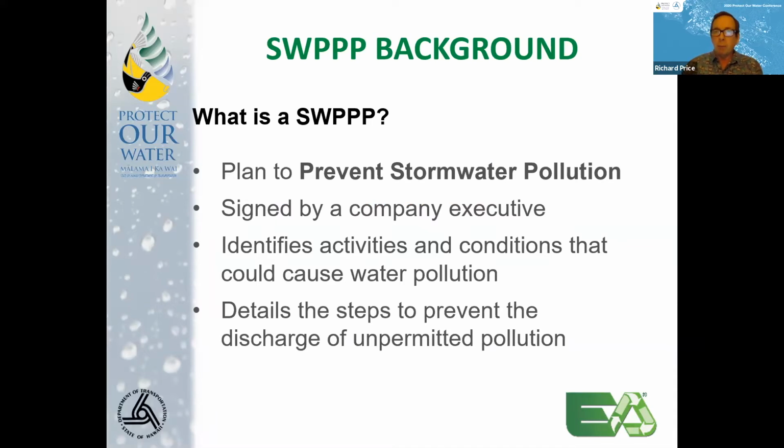That's an important point, because the construction general permit is a federally mandated permit under the Clean Water Act and has mandatory penalties associated with noncompliance, particularly for intentional noncompliance. And so if you, or in more cases your boss, is signing this plan because you told him it's good to go, they are personally liable, and the company is liable for what's in that plan. So it is something to take seriously.